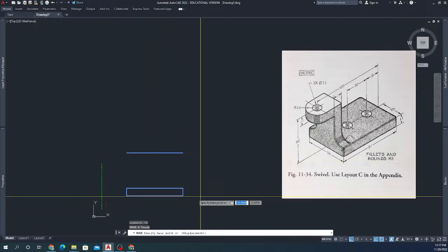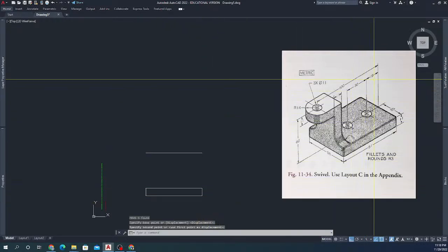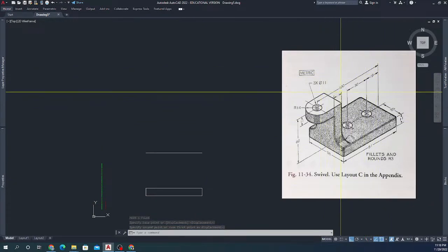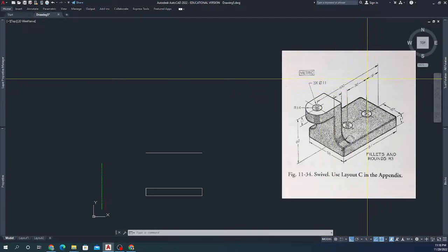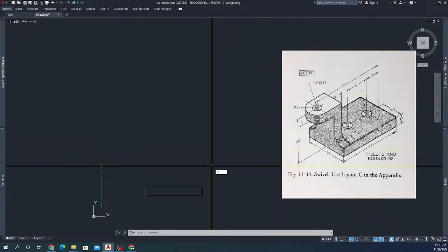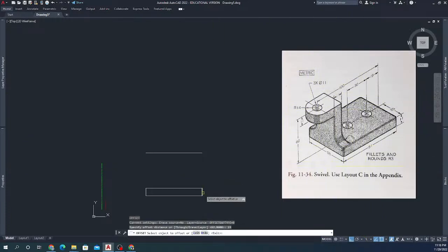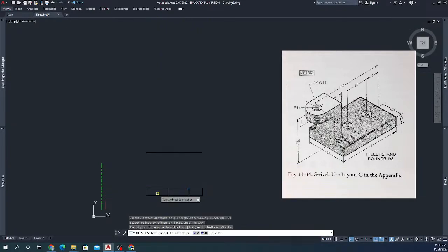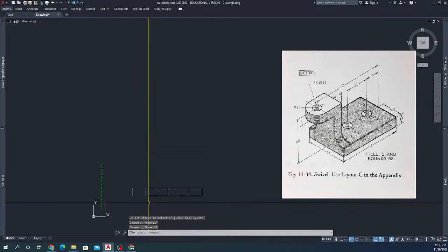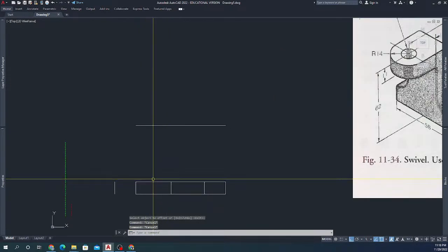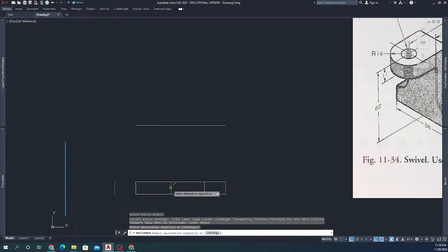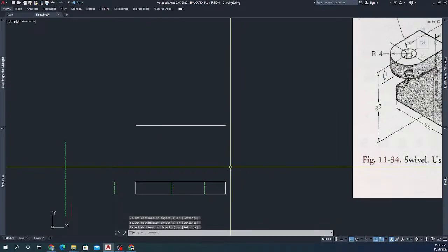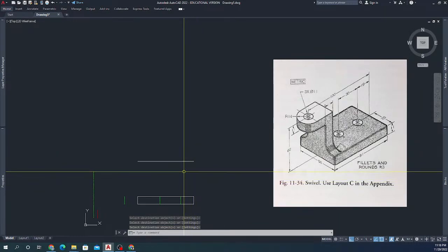I'm going to offset again to get my center line positions now before I draw anything else. So I've got 19 from the back, then 30, and then for my last hole I have 100 millimeters. So offsetting 19, enter twice, then 30, enter twice, and then 100. So all those are going to become center lines. So I'm going to use match properties, MA, click a center line, and those are my hole positions, left and right.